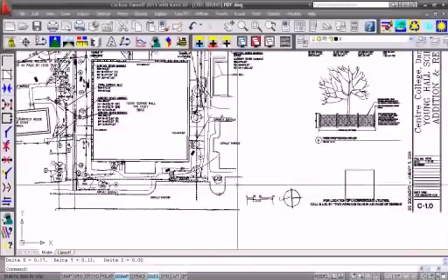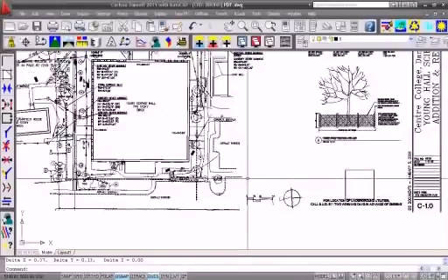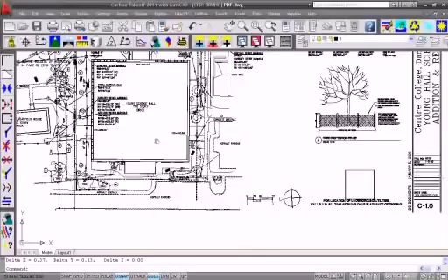All right, so what I want to point out is, there's not a set sequence that we really should do, or is there a sequence that's better practice than others? Yeah, in terms of workflow, you typically would scale the drawing first. You can bring in a PDF, maybe do a drawing cleanup on it, but one of your first steps should be to scale the PDF so all the line work you create is true. You're not doing that after the fact.